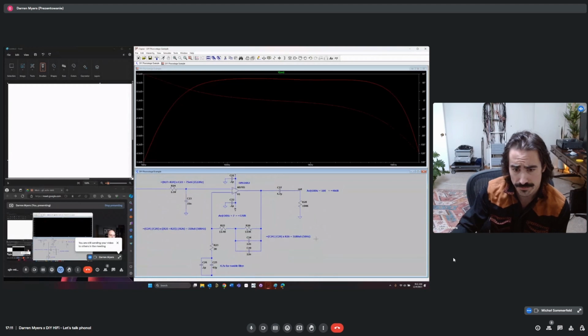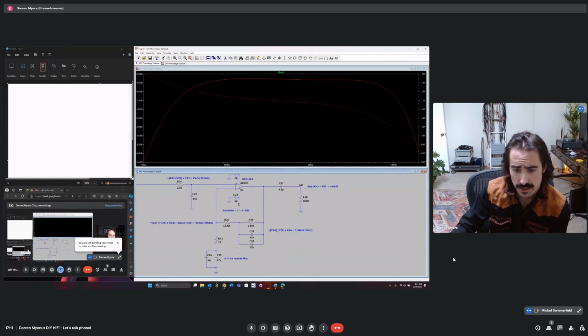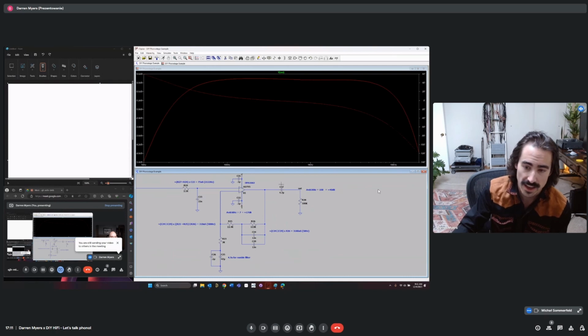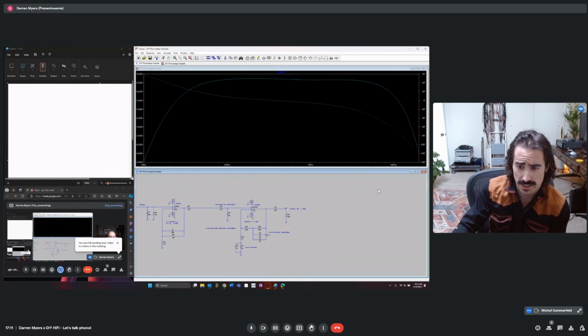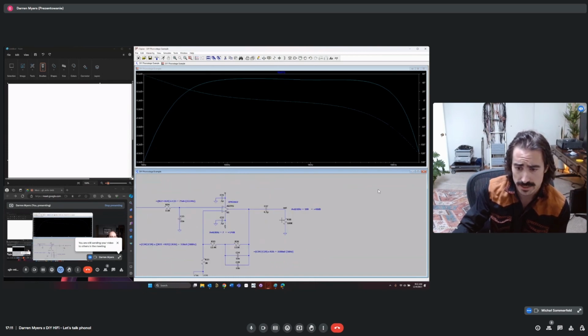Okay, so moving on, we've described our time constants here, how we came up with them. We described why we need to decouple the feedback at DC, and then we have a series capacitor here to block any sort of DC that is residual right here. And this is just in a DIY project where you don't want to mess around.